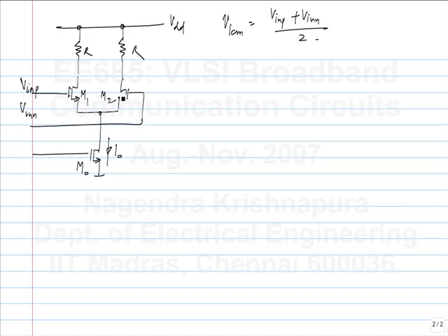So firstly, are we supposed to see Vin P and Vin N both have two logic levels? Vin P and Vin N are the common mode voltage plus or minus some differential voltage. Which is the worst case? When Vin P and Vin N, one of them is high and one of them is low, or when the two are equal? What is the worst case for M0? Is it when Vin P equals Vin N, or when Vin P is different from Vin N?